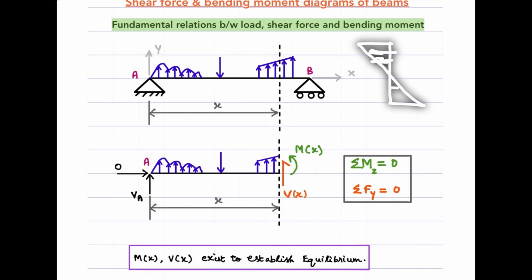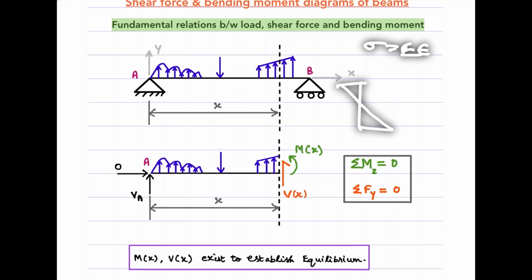So once you get this, one can also get the stress profile as well. How? If we consider Hooke's law holds, we need to take the strain profile and multiply each ordinate with the modulus of elasticity, right? So from that we get the stress profile, which also varies linearly, right, within the elastic range.